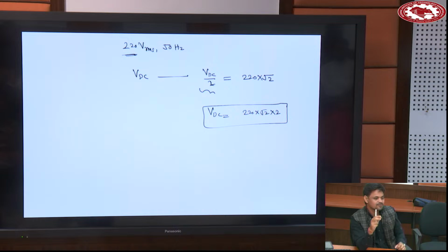Actually, in the inverter you have seen in simulation, this much is the DC link voltage and this much is the AC. Then how is the DC link voltage calculated? Using this formula only. This is for modulation index 1. You have used full, I mean the sine wave is touching 1, duty ratio is touching 1. If you are limiting it to 0.8, modulation ratio is 0.8 only, you require more DC to produce the same voltage. Okay.